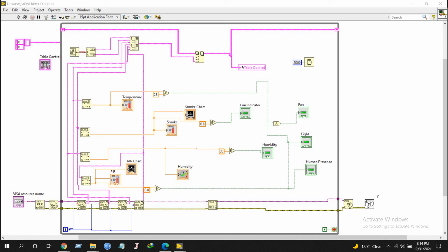These are the byte counts. Here, the time delay function is 2000 milliseconds for the front panel view. Here is the array table. These four are used to convert the string data into number. This is the build array function. It takes the data of the table.